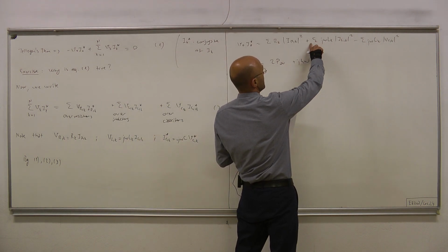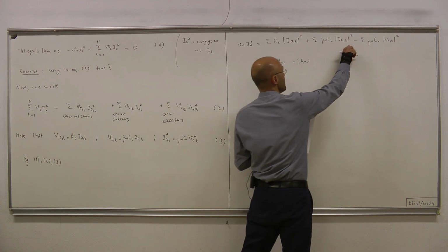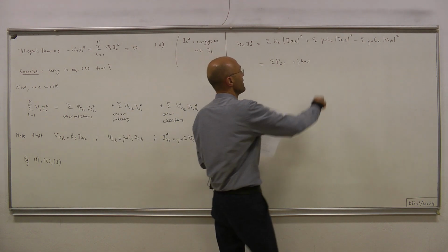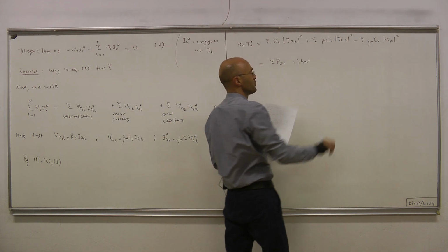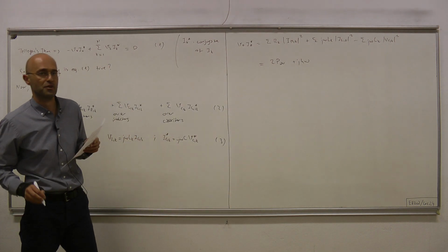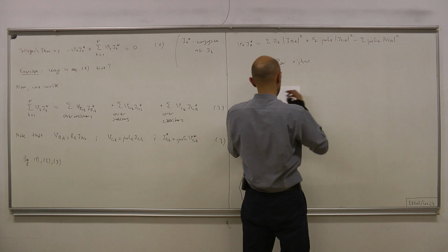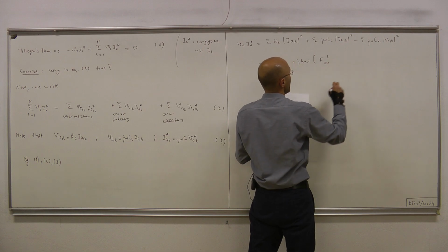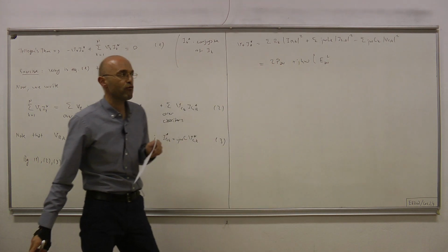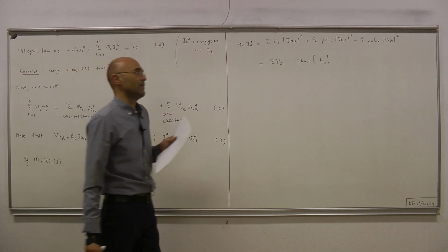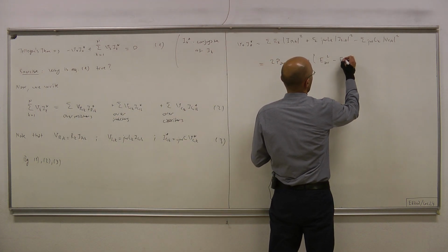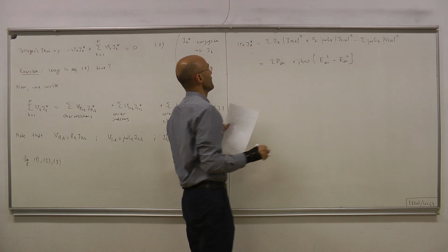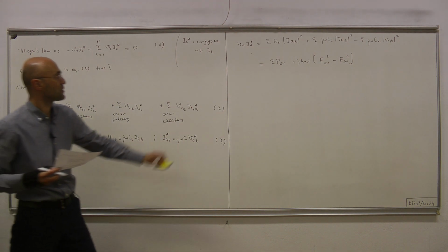Then we multiply by 4 and divide by 1/4, and that 1/4 produces the average stored energies in inductors, summed over all inductors, so that produces our E average superscript L. So we can write here j4 omega E average superscript L, and likewise 4 times E average superscript C, and we have therefore this product V0 I0 conjugate equals this.